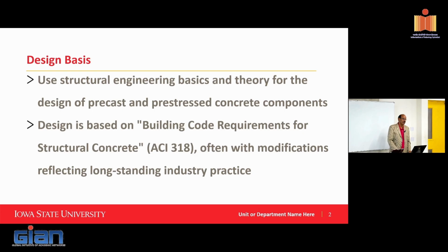So for example, if you're using an equivalent stress block, that equivalent stress block was originally developed for, I don't know, maybe 3 ksi concrete. So that will be 25 megapascal, 20 megapascal. That block, the effective depth value changes if you increase the strength of concrete. So they provide that information, for example. They also provide guidance on when to assume the member to be cracked versus uncracked in terms of using the properties. So the handbook gets into those details.